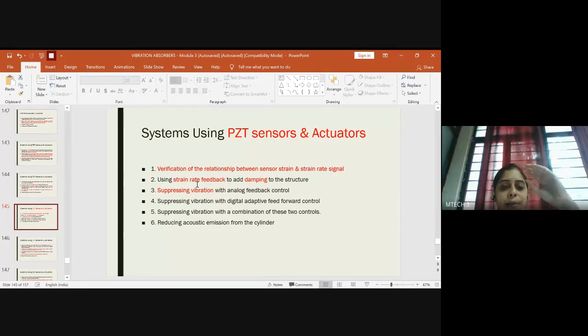So once the vibrations have come to the range where the damping can be added, then you can add. Abruptly, if you have a huge amount of noise, just by adding one damping effect over there, all noises will not be eliminated. At least if the vibrations you're getting are within the acceptable range, then you can add a damper and reduce the vibration based on the feedback.